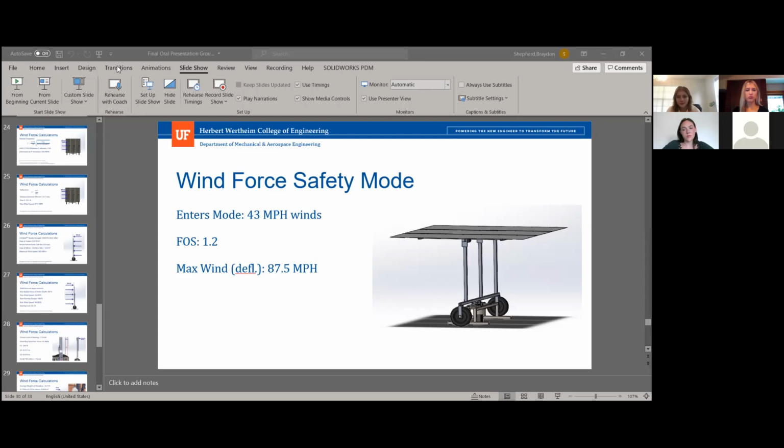Coming from the world of airplane designs, we keep things at 1.5. Unmanned rockets are at 1.25, and those are systems that are severely weight constrained. You're sitting on the ground, you're not really going anywhere, so you don't have weight constraints. I would expect to see a significantly higher factor of safety on something like that, where if this thing falls over, you're shattering a mirror, you're doing significant damage, and maybe the cost is such that that's acceptable, but I would confirm that that's acceptable with your customer. Particularly because as that safety factor goes up, the wind speed that you can tolerate is going to go down, and that limits the utility of a system like this. If you can't survive more than 20-mile-an-hour winds, and it's going to be that windy on a majority of the days, that's a significant problem for a system like this.